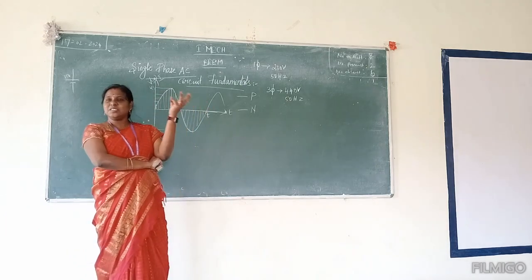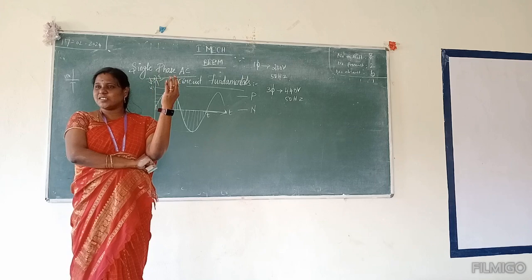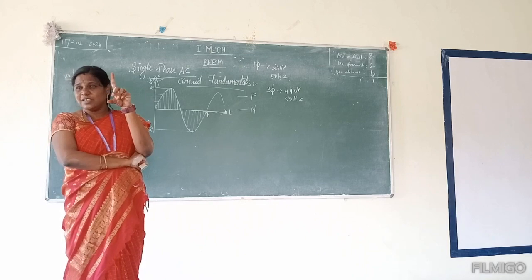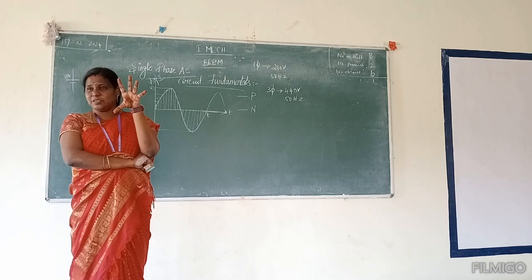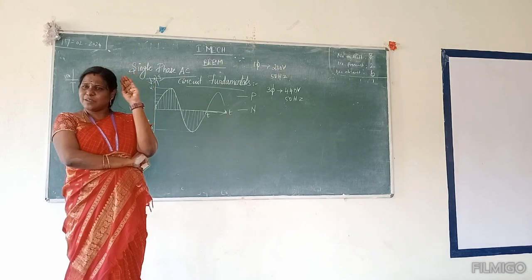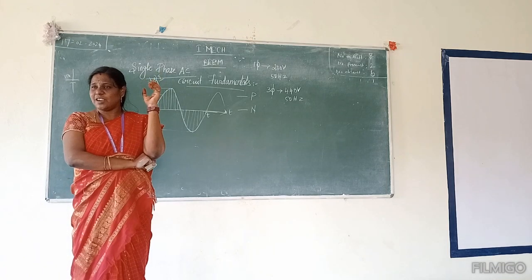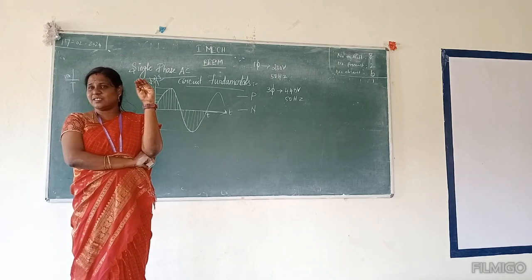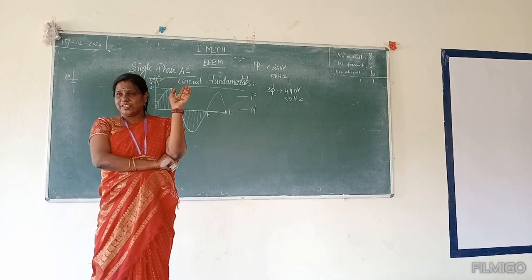Suppose you have a washing machine, AC, motor, heater, iron box, grinder, mixer, and everything runs at the same time on single phase, there will be voltage fluctuations, and it will not handle that load. A single AC is okay, but some houses have three ACs in three rooms, two washing machines, and three TVs. In those cases the electrical load is very high, and all the equipment cannot run on single phase.